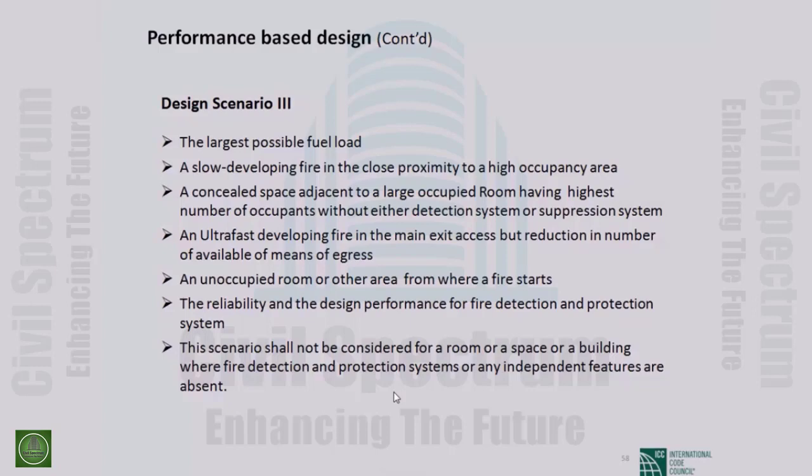For every element, how much time you will get and how much fire safety you would like to give to every part of a structure element. It can be any joints or slabs or partition or everything. You have to design all the things. Then you have to combine all the things, taking all fuel load, all rooms, and the critical condition. You have to design your performance-based detection and performance-based extinguishing system. This is a little bit of idea about the performance-based design system.